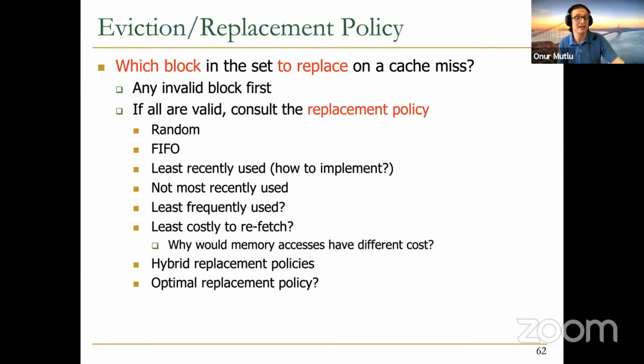You have to have a valid bit because you have to distinguish whether the data that's stored randomly in that particular location is something that you loaded into the cache willingly or something that happened to be there, right? So the valid bit, no, it's not only for system startup. That's also a very good question. There's a question that asked, is it only for system startup? The answer is no, because you may actually decide to invalidate a block for other reasons. And this becomes more complicated, but well, what could the other reasons be?